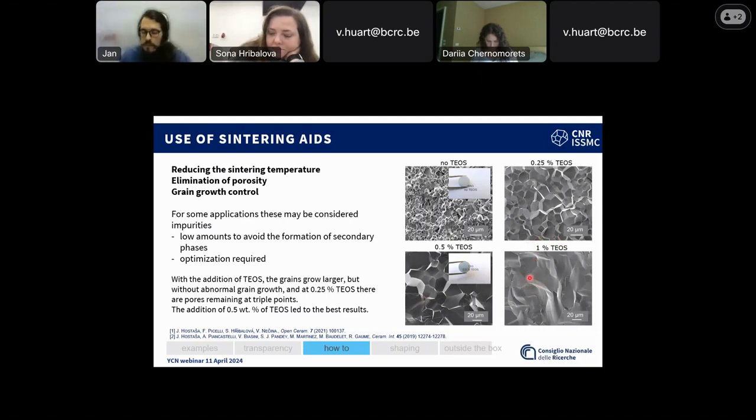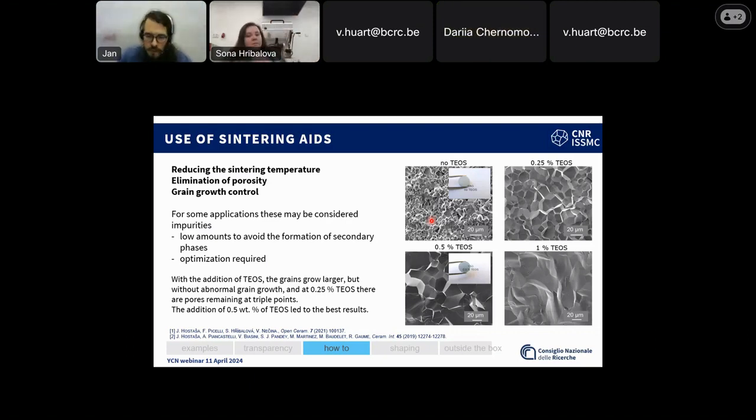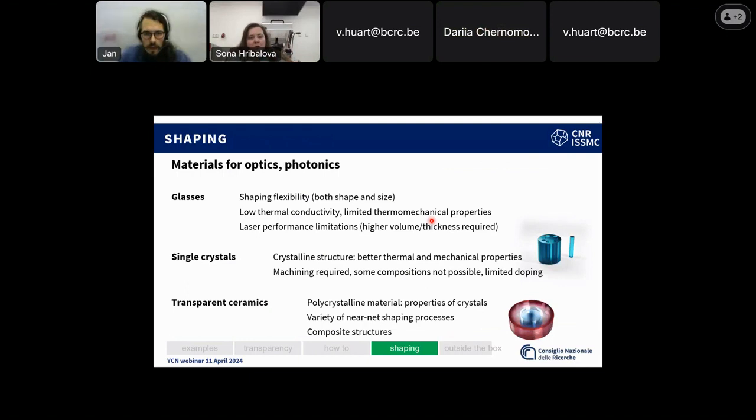And then there are many other approaches, but the point of what I wanted to say was, if you go back to the questions that I asked at the beginning, could my ceramic be transparent? Well, maybe yes, maybe it could. Maybe it's really a matter of how you treat it. If you avoid some impurities, use the right sintering aid and sintering process, and start with fine powders, you might be able to produce your material in translucent or transparent form, and maybe it could be worth it, because there are quite a lot of interesting applications.